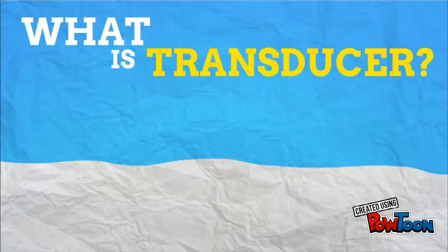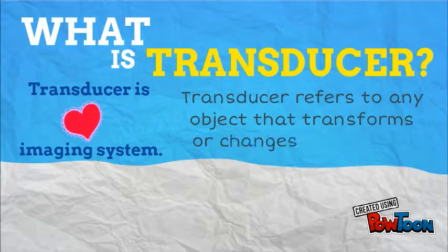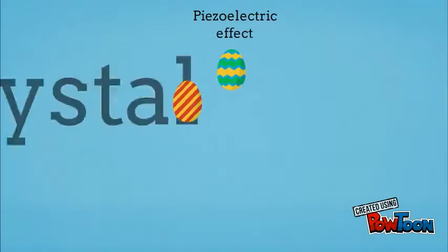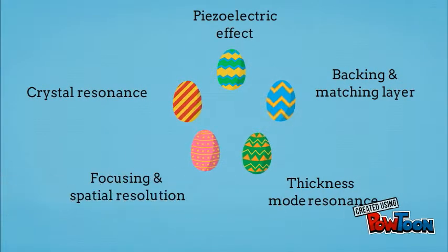So, for the introduction, what is a transducer? For all diagnostic ultrasound applications, the transducer is the heart of the imaging system. Transducer refers to any object that transforms or changes one type of energy into another. This class of transducer provides the basic concepts of piezoelectric effect, crystal resonance, thickness mode resonance, backing and matching layer, focusing, and spatial resolution.